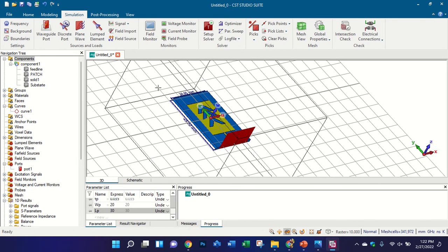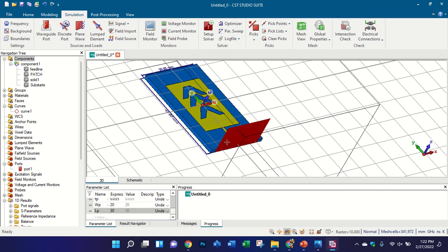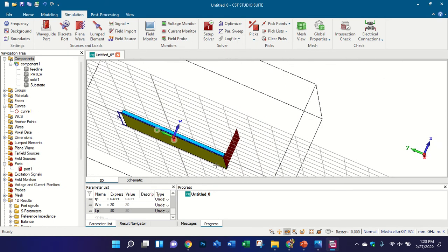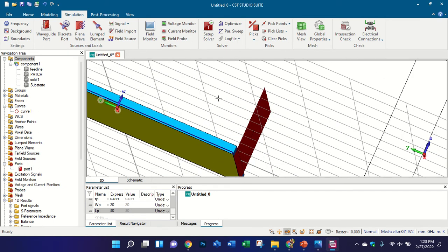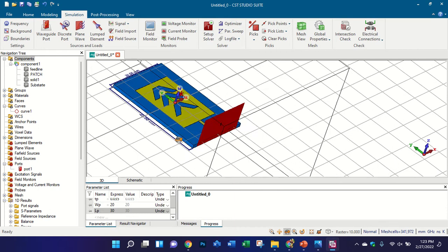In antenna arrays, the radiation pattern is in most cases a directional pattern. And you can use metamaterial, metasurface, or artificial magnetic conductor to control your radiation pattern. Or you can use the CPW technique in this way. But if you use a half or partial ground plane, then it sometimes gives a back radiation pattern.